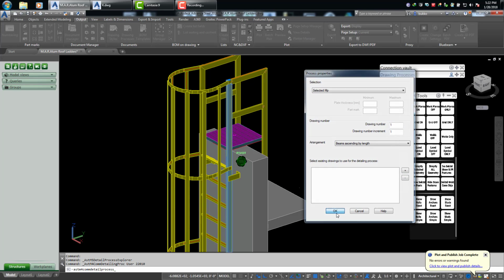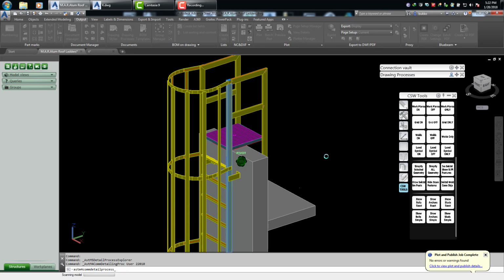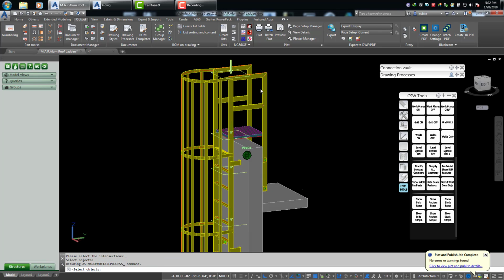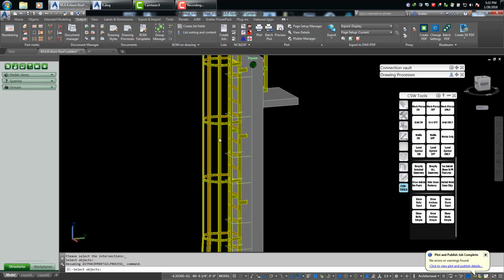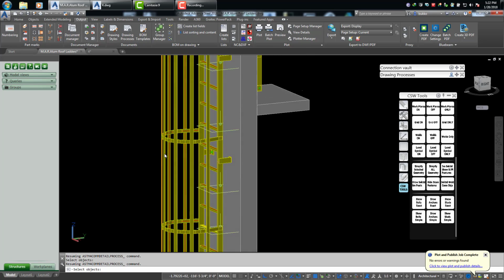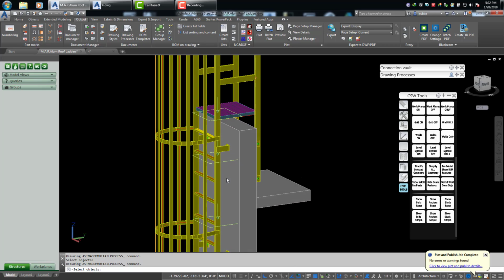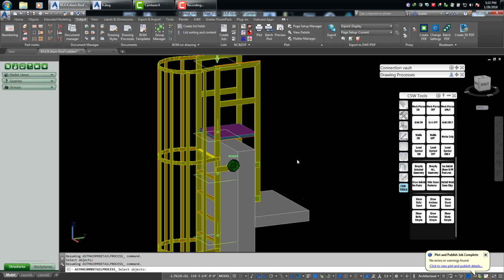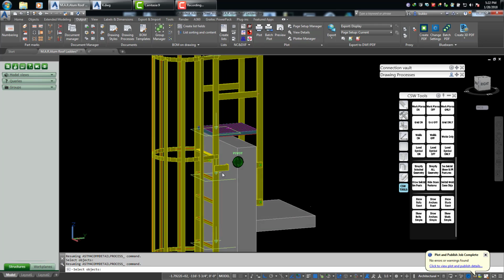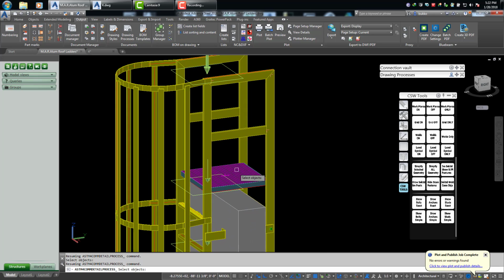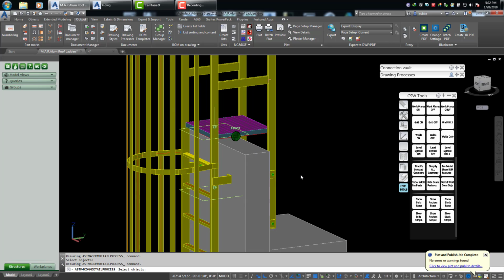It's drawing number 1. Hit OK, and it's going to ask me interactively for the sections. Now, these are the sections that are automatically plotted, and there's a setting in the management tools that allows you to increase or decrease this distance. I can't remember what I've had it set at, but out of the box, I think it's set at like 6 inches or something, which is way too small, and it basically picks every part that's welded to the main part. So you don't necessarily need that with this particular style.